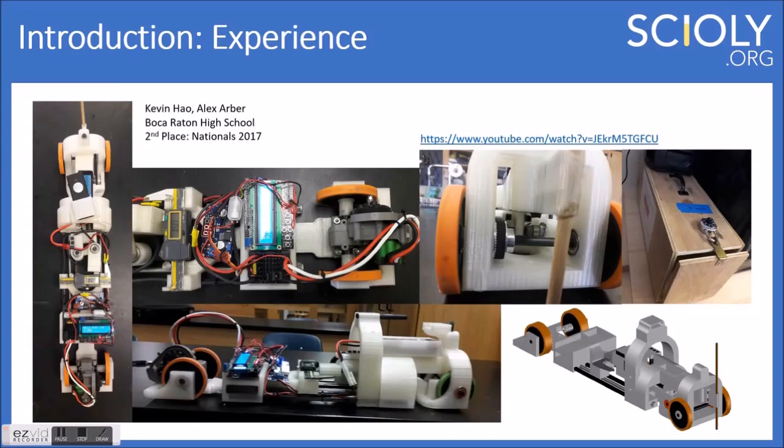You can see the same voltage regulator in here for our electronics. That didn't change from the previous vehicle. The encoder was the same encoder, but if you look at this profile picture over here, you can see how we use this belt system to remove the encoder from the front axle and offset it towards the rear. If we had the encoder directly connected to that front axle, our vehicle width would be larger. We were looking for ways to reduce that.